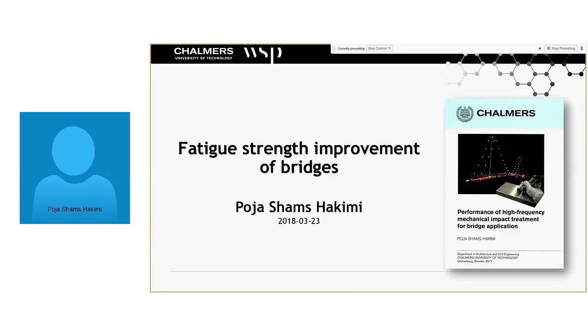I was surprised that fatigue was so governing. I think if fatigue is governing and the details are suitable for this treatment and they are accessible, in these cases the cost saving can be much more considerable than the conventional bridges I have looked at. Because in conventional bridges, the raw material cost saving is not so much, because steel is actually very cheap, while we think that in conventional bridges the welding costs that can be very much reduced are the most